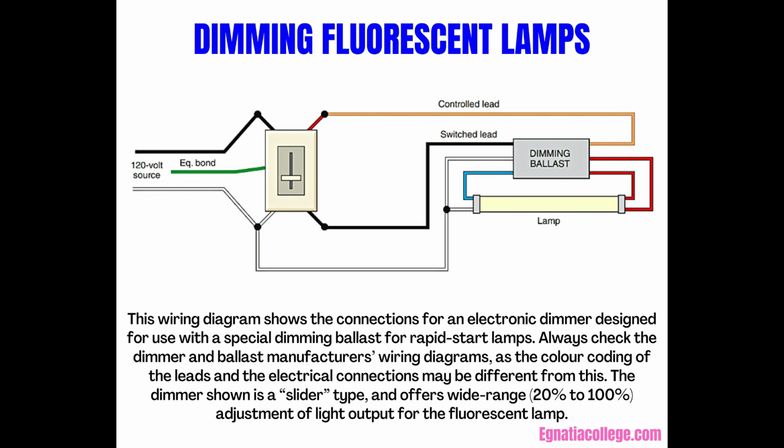characteristics between lamps. Because incandescent lamps and fluorescent lamps have different characteristics, they cannot be controlled simultaneously with a single dimmer control. Do not control electronic ballasts and magnetic ballasts simultaneously with a single dimmer control. Always read and follow the manufacturer's instructions furnished with dimmers and ballasts.